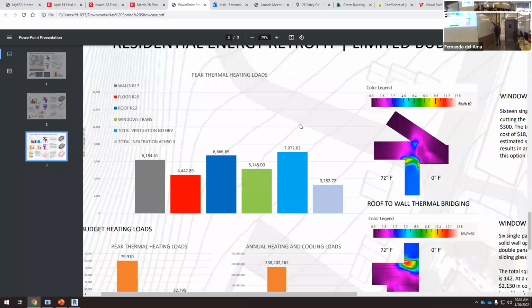This is the peak load times hours per day times number of days. If in January I have this peak load, I use my system 10 hours per day, and January has 31 days, so that is the number that we'll have in this part.